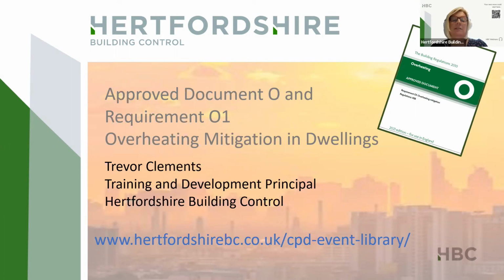Okay, final two questions. Would paragraph 3.6, security, generally rule out the use of bedroom windows for cooling in a new bungalow unless the builder developer is prepared to fix full height railings or shutters? Yeah, in a bungalow, it's a good point. Yes, it's as simple as that, isn't it? They are going to be accessible windows, to bedrooms, so you've got to make them secure, and that's the only way you're going to do it, with some guardings or shutters which are ventilated.